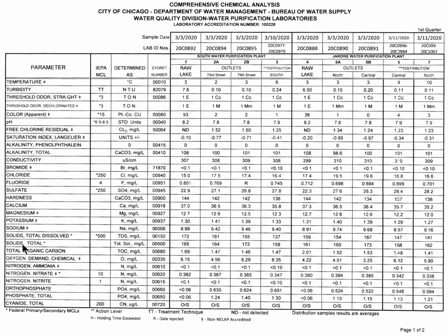This includes floatables and other items like that. Total organic carbon, oxygen demand, chemical oxygen demand, ammonia as nitrogen, nitrate as nitrogen, nitrite as nitrogen, orthophosphate, phosphate, and cyanide. Now this column here is the maximum limit as recommended by the Illinois EPA.